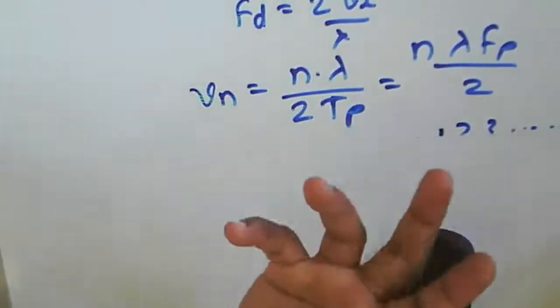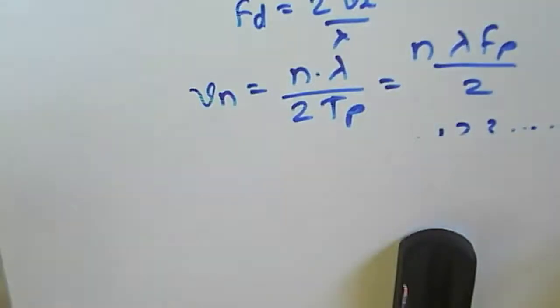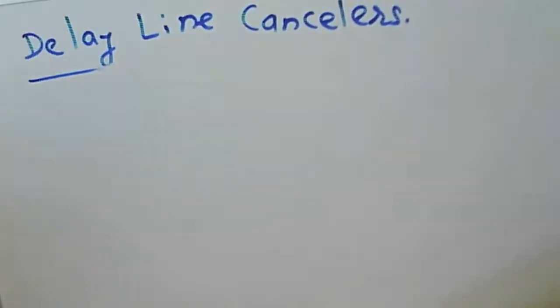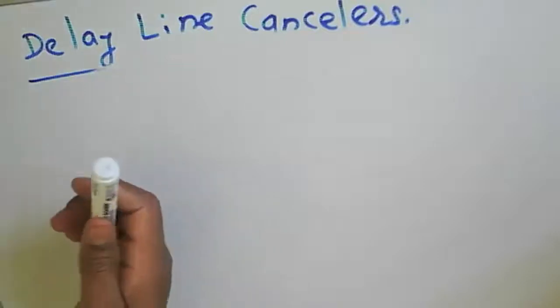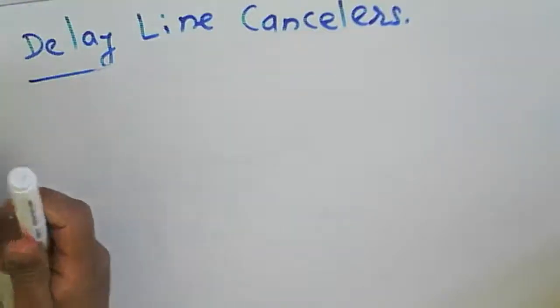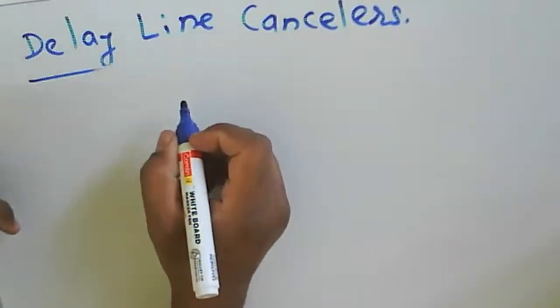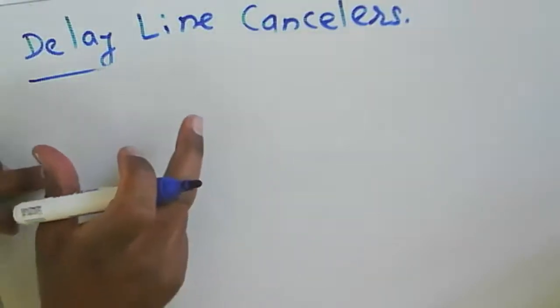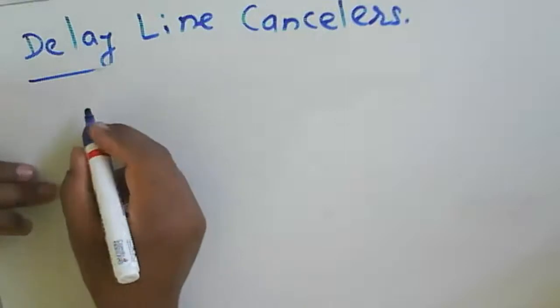This means there will be a moving target observed, but that moving target is cancelled with the undesired clutter at zero frequency. So the target is present, but it is not able to be displayed on the display device because of a blind spot. To avoid this limitation of the MTI radar, we need to operate the radar differently.